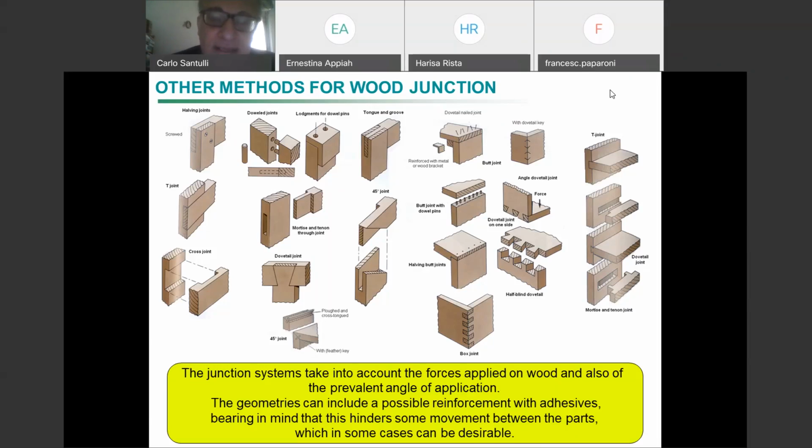The example I was making is a kind of self-assembly. I put screws into metals, I put wood into wood, and I remove glue as much as possible. Otherwise, wood would be contaminated, and I am not able to use it, for example, for energy recovery, and even less for recycling, which in wood means mechanical recycling, because in thermoset materials, since they don't soften, the only recycling that can be done is mechanical recycling. So I grind everything and I put it into something else. So from wood, I'm quite smoothly going into composites.